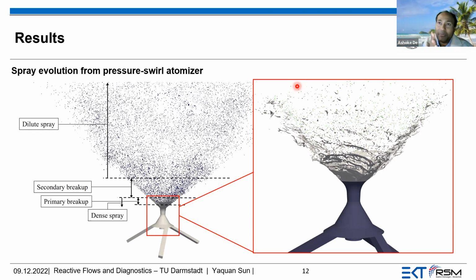See, in the Eulerian phase there could be evaporation, right? The ligaments and all these things can evaporate, and their combustion may also take place. Another portion would be when the ligament converts to dilute particles, which are again ready for combustion. So there are two portions where combustion can take place. Now, how are you thinking about that? Once the ligament breaks and you get the particles, that portion is clear: there would be combustion and the ESF would work. But the ligament may also evaporate if you have a high temperature. So how is the Eulerian field going to be coupled in that part?